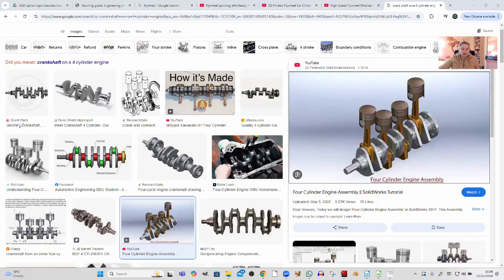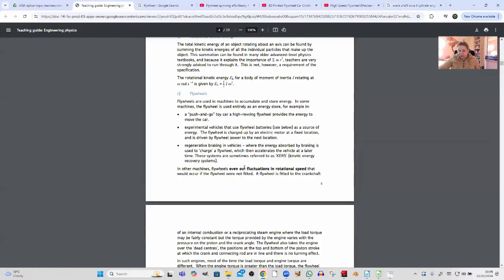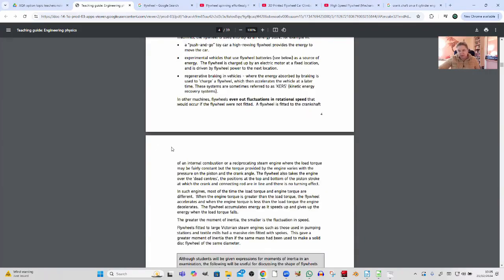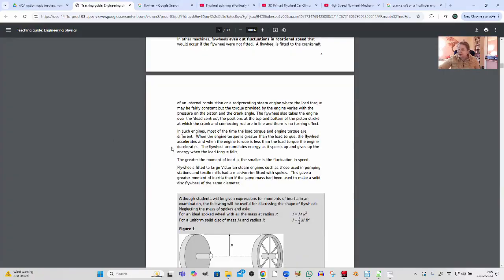Right, okay. So there's this idea then of a crank. Let's go back to our thing, which evens out. Can you see there in bold? It's obviously very important. It's probably going to come up in your exam. Evening out the rotation speed, the fluctuations caused by the fact that your power is not being delivered smoothly. It's not like that electric motor at all. Okay, so heat engines do not deliver power smoothly. Right, not mostly, they don't. Some heat engines do. Jet engines are quite good.